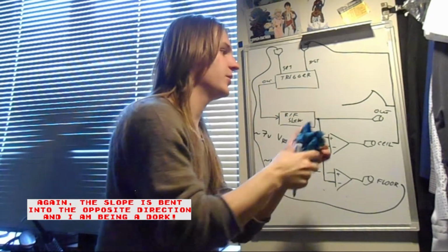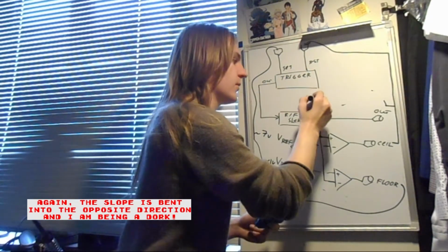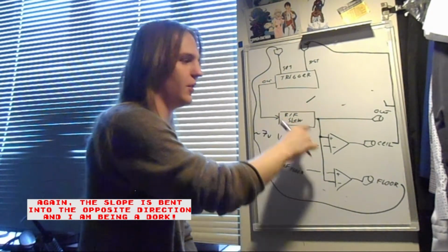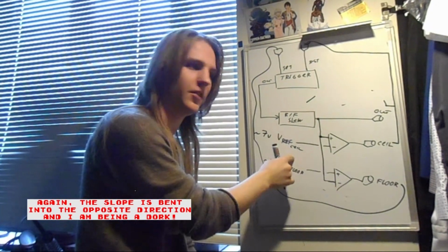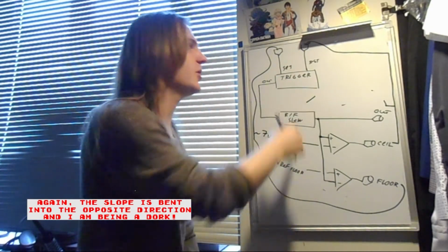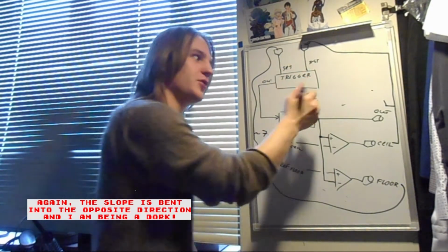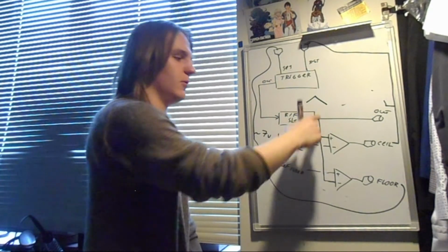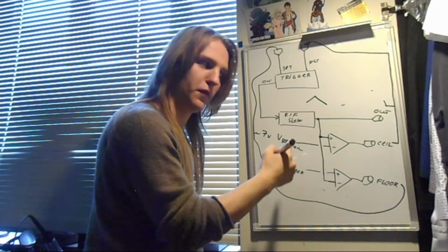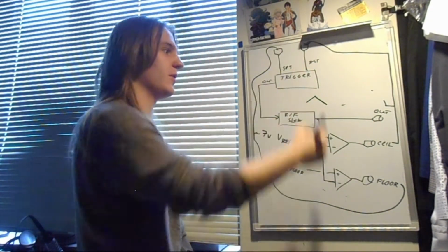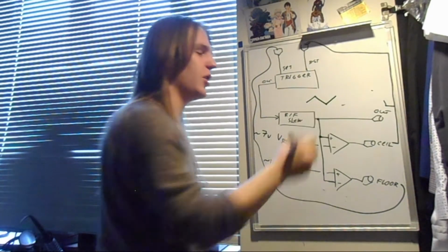It goes back to the set and it sets the function to 1. The function starts rising. It rises until it crosses the voltage reference ceiling, which then resets the function and puts 0 into it. The function starts falling until it crosses the voltage reference floor, which then sets the trigger to 1 and it starts charging.